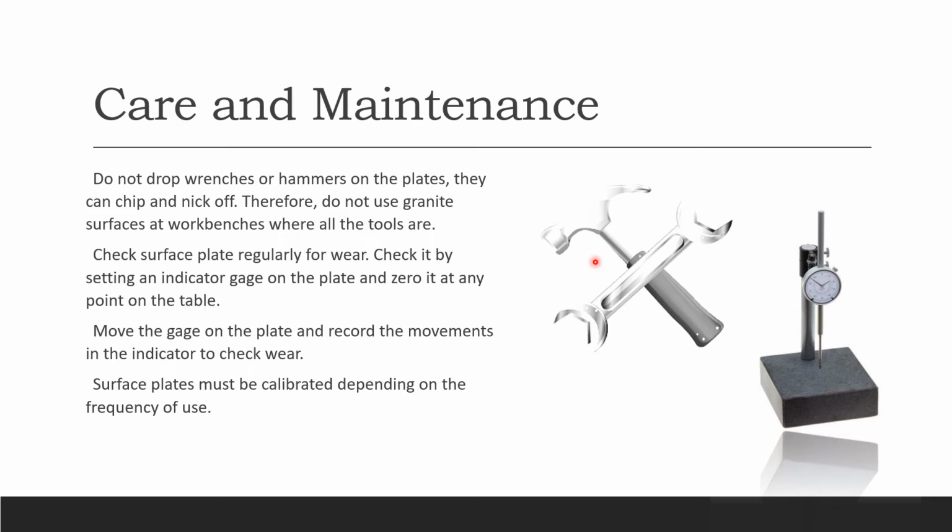Care and maintenance again: do not drop your wrenches and your hammers on the plates, because they can chip and nick off the surface plate. So therefore, do not use a granite surface as a work bench where all your tools are. Make sure you check the surface plate regularly for wear.